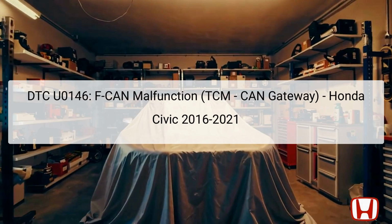DTC U0146 refers to an F-CAN malfunction, specifically affecting the transmission control module, or TCM, as located within the Honda Civic models from 2016 to 2021. F-CAN stands for Flexible Controller Area Network, which is integral for communication within the vehicle's electronic systems. The CAN gateway acts as the communication bridge that helps the TCM transmit and receive information regarding various operations, ensuring